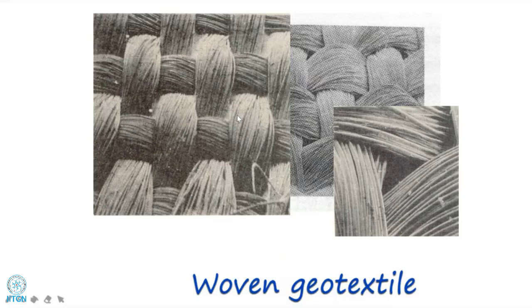Now, you also know from your basic engineering knowledge that for this material, we should know its thickness at failure. Isn't it? That's how we define the strength actually. The load divided by the unit area at failure is the strength of the material. In this case, it's very difficult for us to determine the strength. I mean, the thickness is so small actually. And if we conduct a tension test, the thickness will vary, and that variation is going to be very, very difficult for us to find out, to measure. For common engineers, very difficult actually.